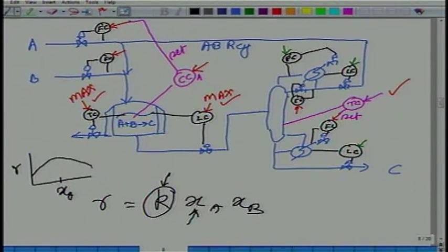You really cannot operate right there, you can operate slightly below it. The reason will become clear to you later on. So maybe you will say, okay, 40%. Why 40%? Because that maximizes my reaction rate, which maximizes conversion, therefore lesser boil up, lesser energy requirement for recycling the unreacted reactants. Does that make sense or no?